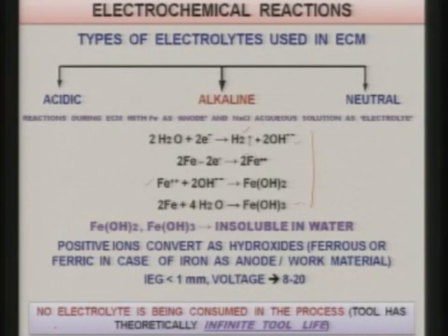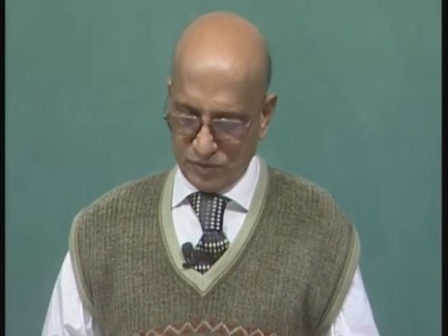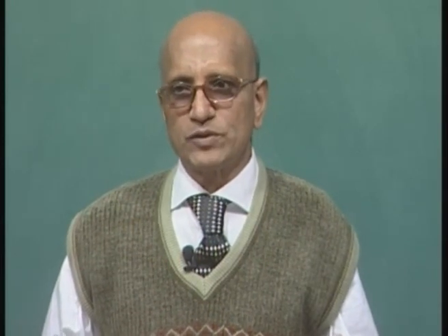Hence, the concentration of the electrolyte that changes is due to the loss of water during the electrolysis process. Hence, we have to maintain the conductivity of the electrolyte regularly to have predictable material removal from the workpiece. And another point is there are no forces acting on the tool, temperature is also not very high, there is no sparking. So, there is no loss of material from the tool. Since there is no loss of material from the tool, theoretically the life of the tool is infinite, although there are some practical reasons because of which the life of the tool in ECM is finite. We will discuss this particular point later in other lectures.